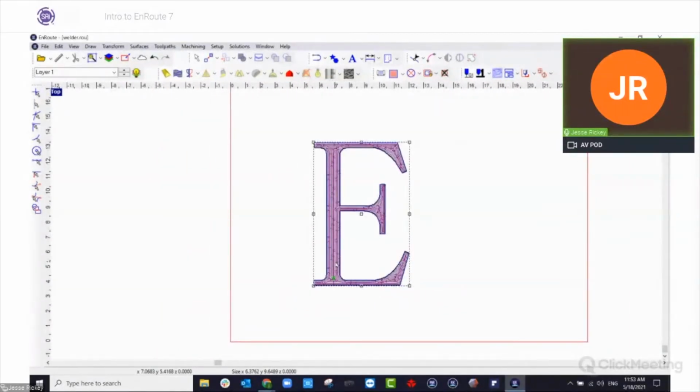We've also added different tools for the fabrication style cutting. So inside here we have kerf comp, we have kerf marking and kerf fill, which we did not have in previous versions. So in previous versions of 6, the engrave option in that looked as if it were for a router.